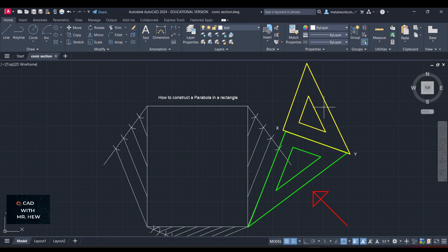Then you would use your right hand to hold down the yellow 45-degree set square. You would use your left hand to slide the green 30-60 set square to the next point, which is here, the intersection of this line and this line. When you slide it there, then you would use your pencil to draw the line using the 4H pencil. Then you would repeat the process for the next arc, where this arc intersects this line.